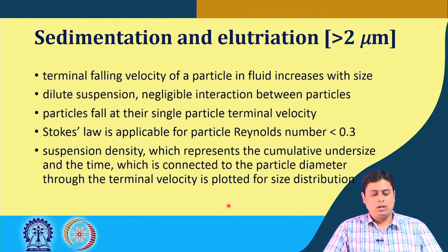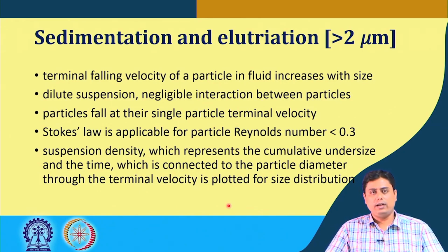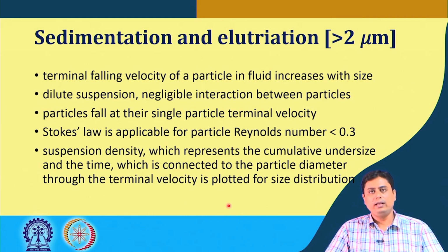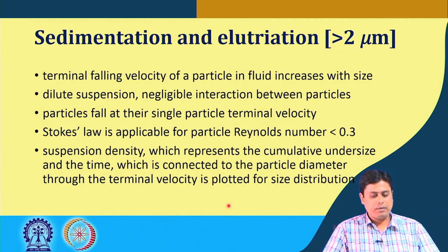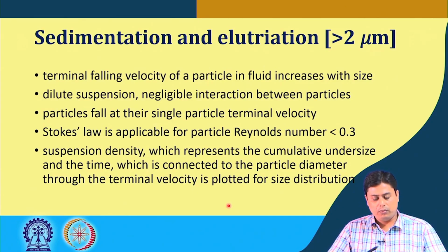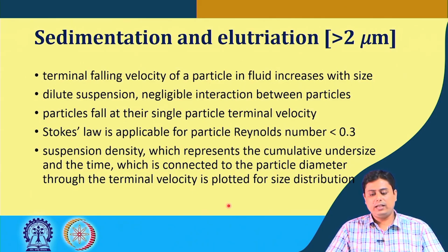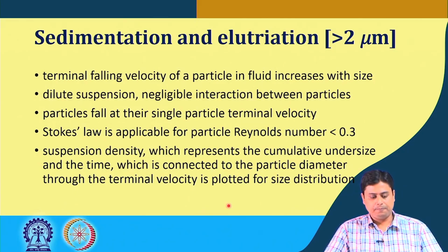Here, the principle of this sedimentation process is based on the fact that the terminal falling velocity of a particle in a fluid increases with size. If you remember Stokes' law, as I mentioned, a prerequisite fluid mechanics knowledge that you need for this course, you would understand that this terminal falling velocity is essentially dependent on the particle size.